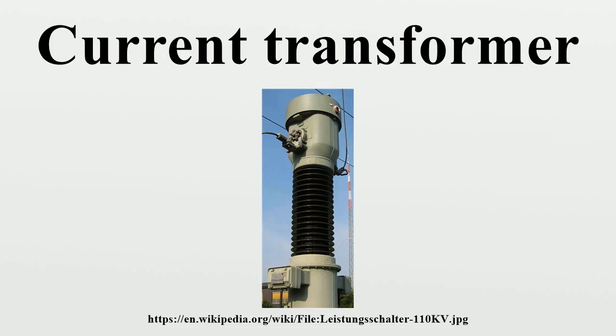Low-voltage single-ratio metering current transformers are either a ring-type or plastic molded case. Split-core current transformers either have a two-part core or a core with a removable section. This allows the transformer to be placed around a conductor with the minimum disturbance. Split-core current transformers are typically used in low-current measuring instruments, often portable, battery-operated, and handheld use. Current transformers are used extensively for measuring current and monitoring the operation of the power grid, along with voltage leads.